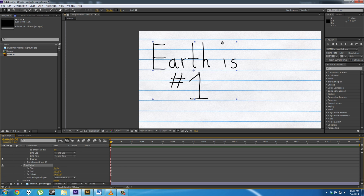And the way that the trim paths work is that we have two ways that we can have the paths be drawn on, simultaneously or individually. If I were to animate them simultaneously, obviously, all the paths would be drawn on at the same time. Of course, unless you have a million hands, that's not the way handwriting works. So, what we're going to do is change that over to individually.